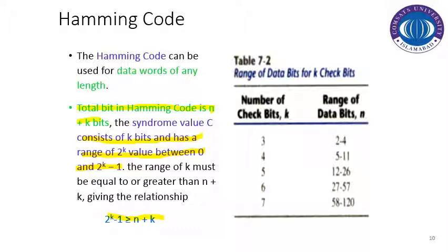That is, the placements in the data that satisfy 2 raised to power n notation, and we computed those parity bits by constructing some exclusive OR operation between some specified bits, and we store those parity bits with the data bits. Then we compute the check bits in the same way in which we computed the parity bits, and